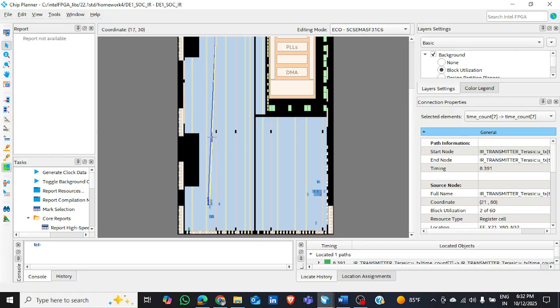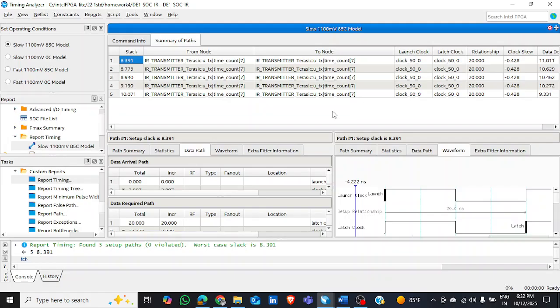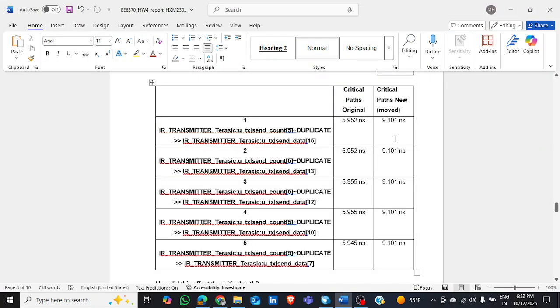So this internally increases the data delay and also the slack times, but it's all well within the range. The design doesn't drastically fail as we saw in part 1b where we changed the clock to 2 nanoseconds. So we'll just be closing at this.